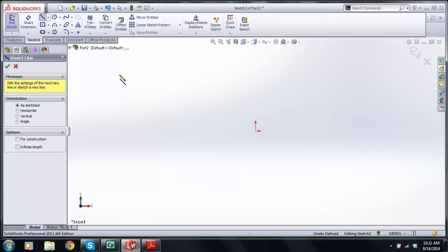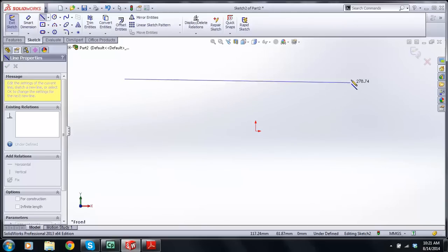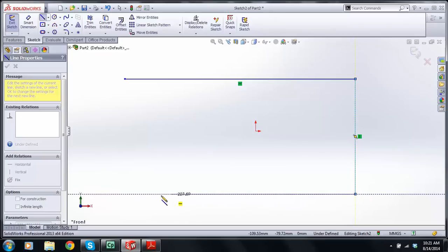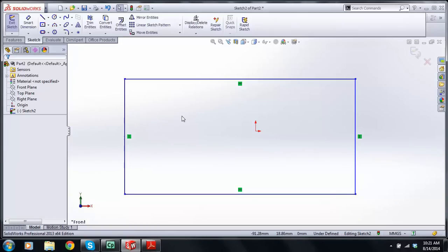I'm going to draw a line. I'm going to bring it over here, snap to the horizontal, snap to the vertical, and let's see, can I complete. Now look at this. This is called object tracking. I haven't pressed a button there yet. I bring it here and just highlight below here, and it will complete that square. I click and then I go up to there.